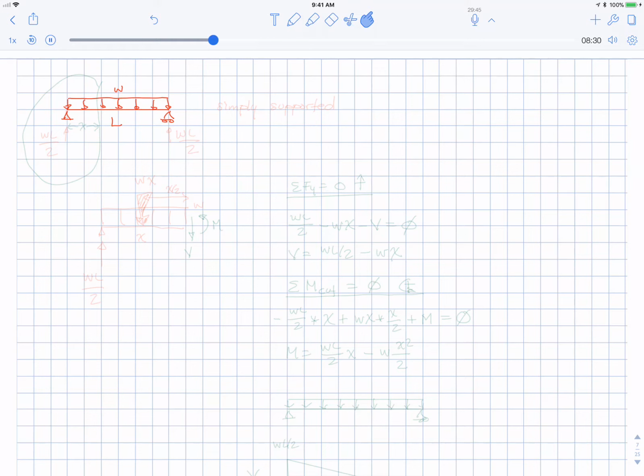these over and over. This type of beam that has a pin and a roller on the two ends has zero moment at the two ends, and we call this simply supported. I don't know why it's called simply supported. I guess because there's no moments on the two ends and it's the simplest way to support a beam. But we always say simply supported for this.